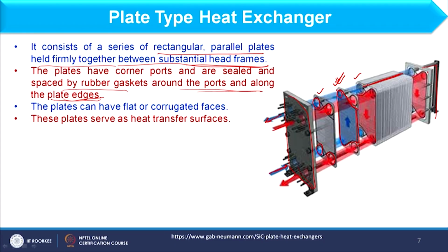Okay. So, what will happen? Whatever cold fluid is coming, if you see this particular plate, here we have the gasket, and the gasket closes this corner and closes this corner. Okay. So, whatever cold fluid is coming, it will spread over this plate and exit from here, because it cannot enter this corner or this corner.